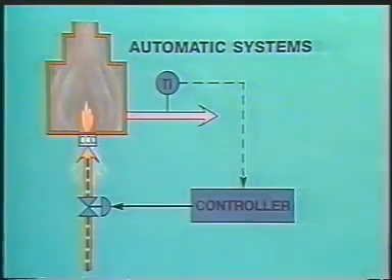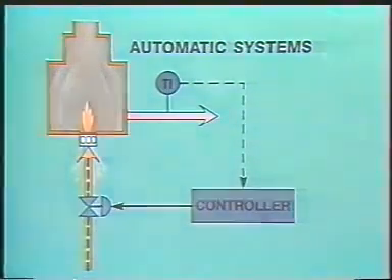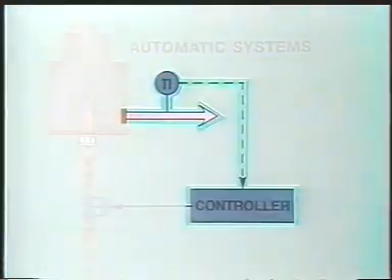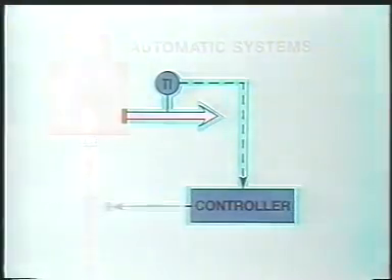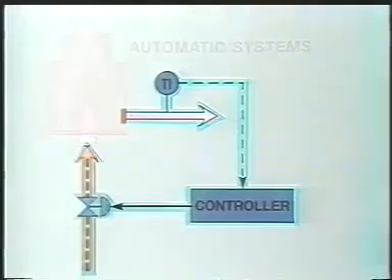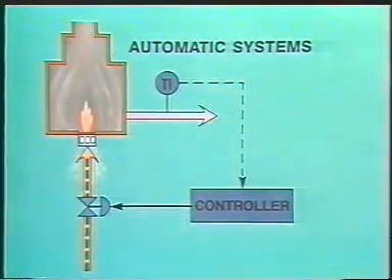Let's consider an example. In an automatic system, the controller adjusts the fuel flow to the burners based on the outlet temperature of the charge. Now, if the measuring or transmitting instrument sends out a faulty low temperature signal, the controller will automatically increase the flow of fuel to the burners, trying to compensate for the apparent decrease in outlet temperature. This, in turn, will cause the furnace to overheat and could cause coking in hot spots.